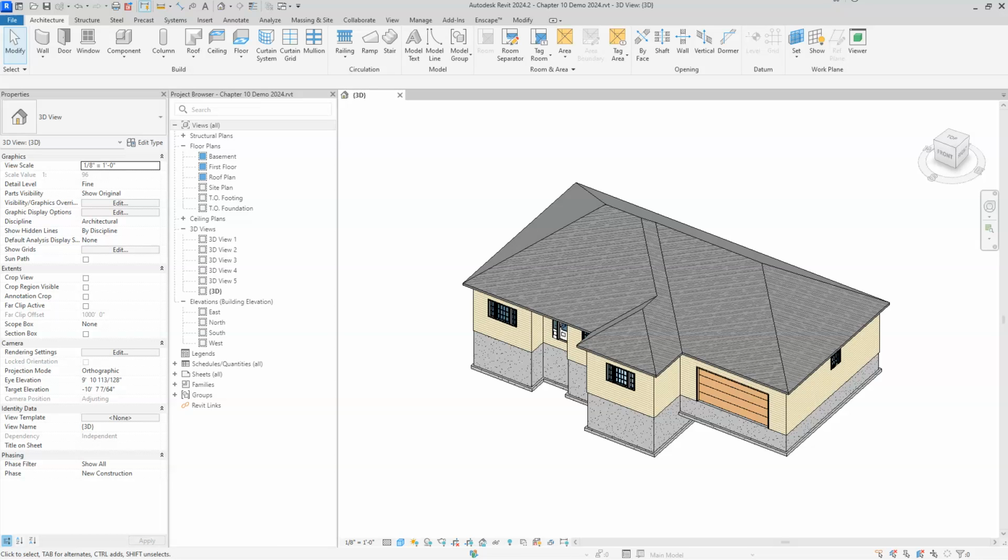The practice you'll be doing from the book this week is going to have you place a structural floor, and it's also going to talk about how to place a second floor over the top of it in the form of tile. And that's a pretty good strategy. We use that quite a bit in commercial design because it gives you the ability to create different floor types in different rooms, which is pretty common. In most buildings, you're going to have some areas that might have wood, some areas that might have carpet and other things. So today, though, we're just going to be focusing on placing a single floor in a residential application.